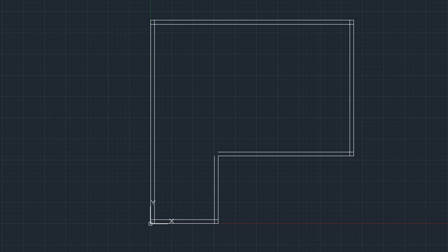We have our inner lines representing the thickness of the walls. However, they're untidy. Some of the lines don't meet, while others overlap. We can tidy these lines using the fillet command. The fillet command is used to generate curves. However, if you create a fillet with a curve value of 0, it pulls lines together or shortens them accordingly. This has the effect of neatening our walls.